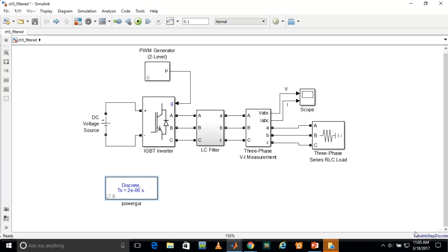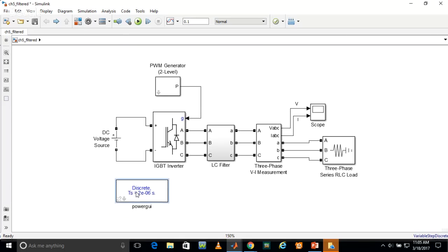At that point, the harmonics present are only of 11th or 13th order, the highest frequency present in that signal. So the filter requirement for L and C will be reduced, and we can get a very cheap filter. So this is how we make this whole system with a filter circuit, and how we calculate the harmonics present in that signal.